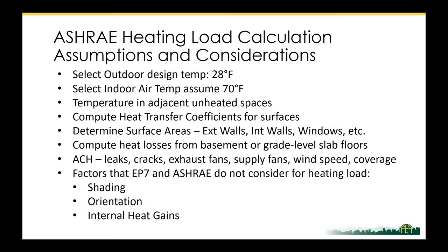We need to determine surface areas of exterior walls, interior walls, and windows. That was the takeoffs that you saw in the plans. We also want to compute heat losses from basements or grade level slab floors. In this case, we're on the second floor. We have a unit below it, and we're going to assume that it's 70 degrees in that unit as well.